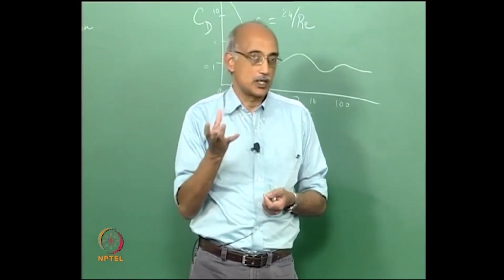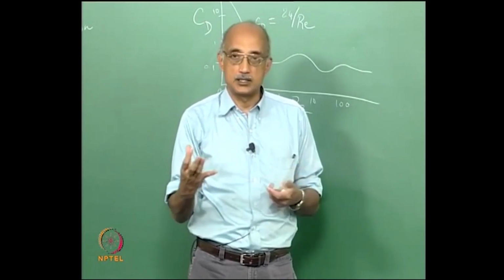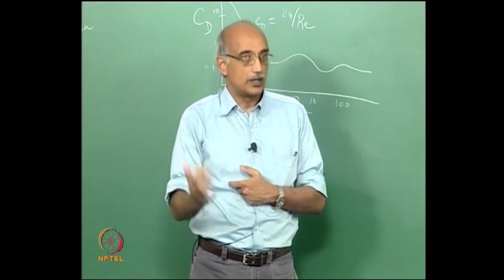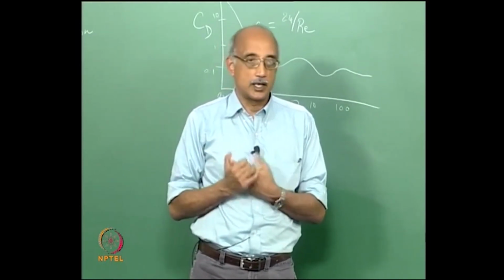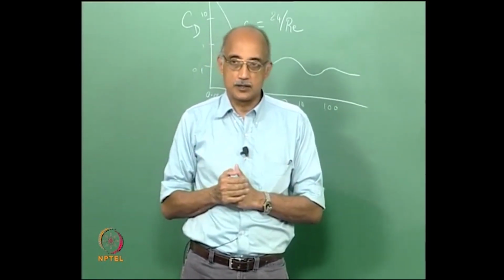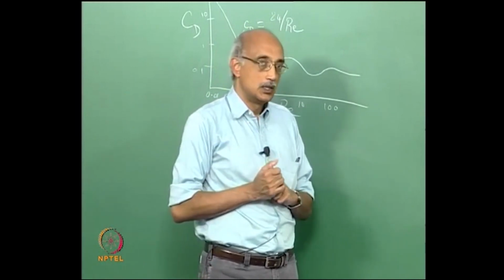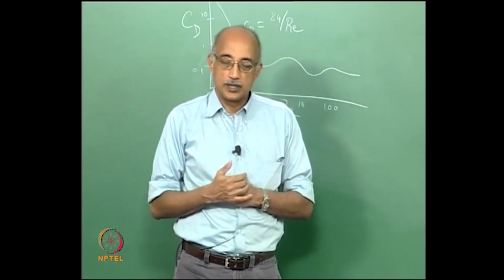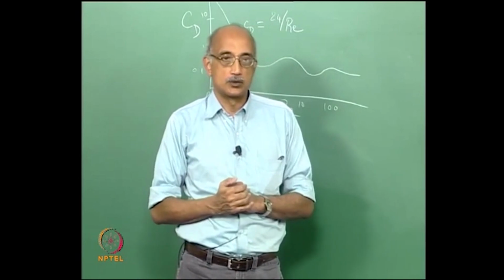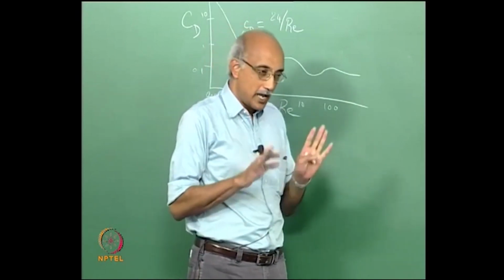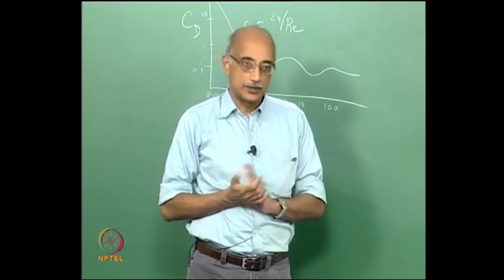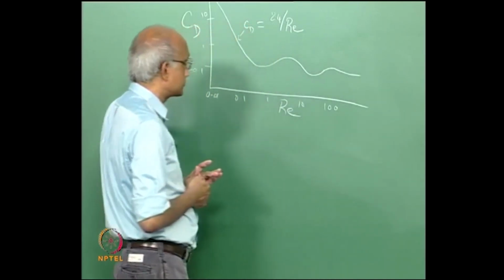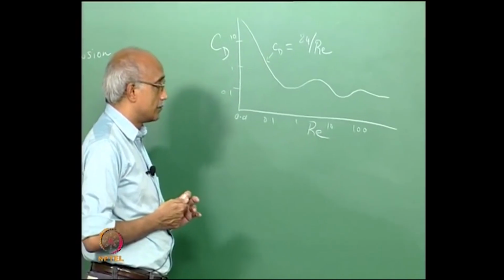If the object is impacted by several eddies in a period of time, it will experience high drag, but there may be periods of time where, given the unpredictable nature of fully turbulent flow, the particle may experience low drag. But if you integrate drag force over time, essentially laminar versus turbulent does not have a significant influence on the drag force that is experienced by the particle.